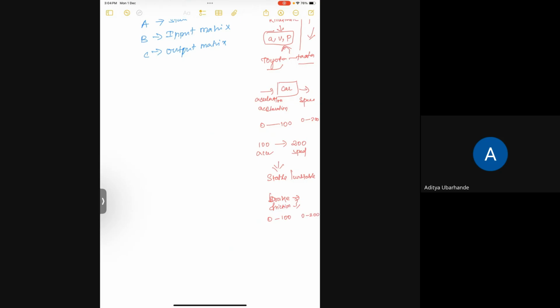But if I just want to do some control in my household, I'm not very fond of accuracy. If the work is done, that's okay. With minimal effort, then I can go with transfer function. No problem. But the main thing is, for a multiple input, multiple output system, you cannot use transfer function at all, even if you want minimal control.